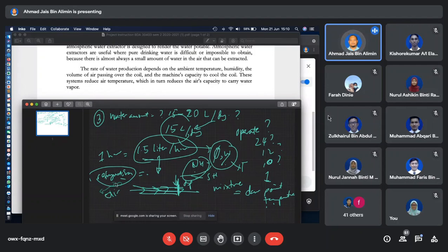The surrounding air is your input, and the air that you push into the system has its own moisture. The question is how you're going to extract moisture from the surrounding using the dew point temperature concept, and how you are going to control the temperature of the incoming air, which is by cooling it down. How? Using the refrigeration system.